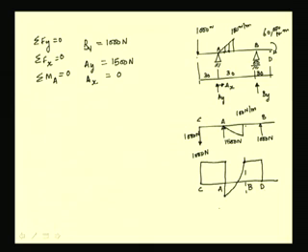On the beam. Now from this shear force curve we can determine the area under this curve, and we can use the same to construct the bending moment diagram. So at C we have a zero bending moment.